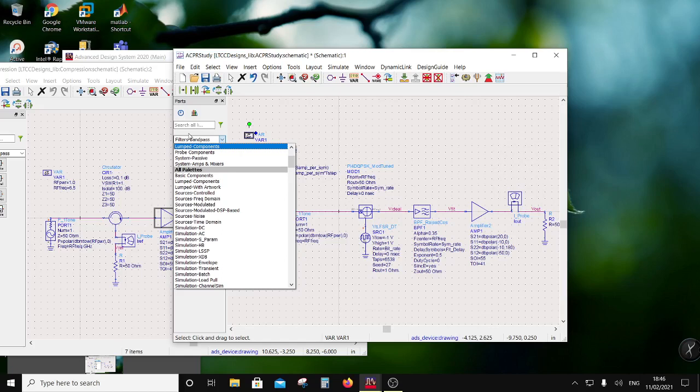Now if you do this in time domain, what's the problem? The problem is you have a time period which is from baseband, but your sampling per cycle or sample rate is from the carrier frequency. The carrier frequency may be in gigahertz. So if you take 10 samples per cycle of, let's say, 2.5 gigahertz, or 6.5 gigahertz, then how many samples would you be having?